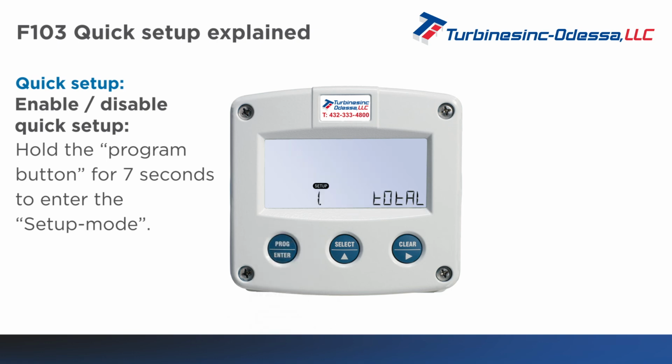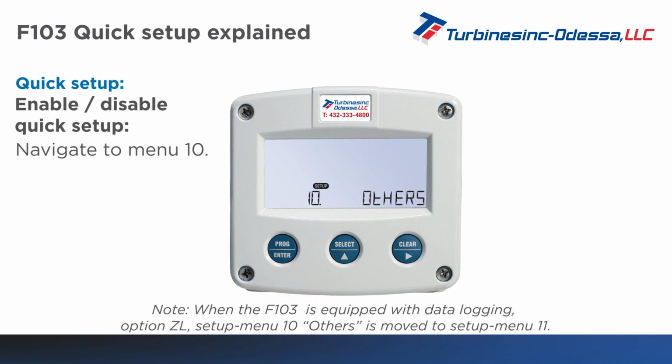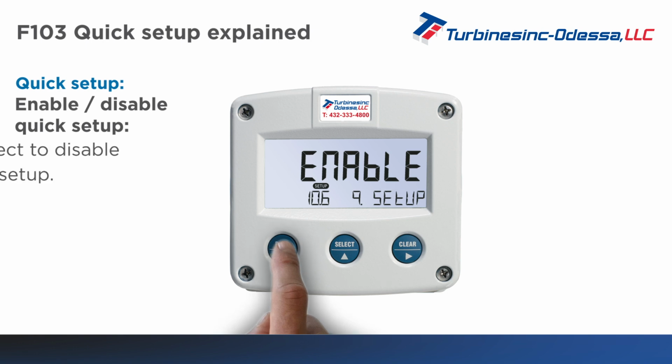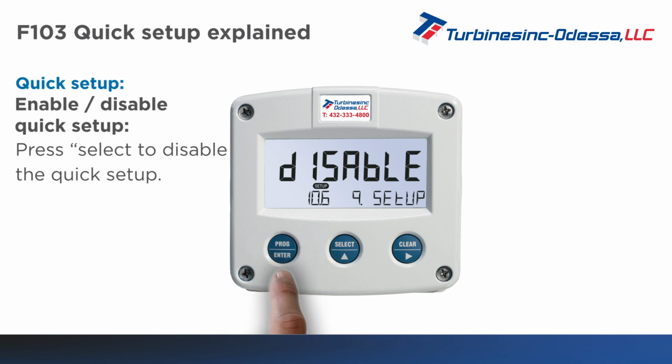Menu 1 Total appears. You can use the Prog, Clear and Select buttons to navigate through the menus. Use Prog to navigate to Menu 10 or 11 Others. Note, when the F103 is equipped with data logging, option ZL, Setup Menu 10 Others, is moved to Setup Menu 11. Use Select to go to Menu 10.6 or 11.6 Quick Setup. Press Prog to change this setting. Press Select to disable the Quick Setup. Press Prog to store this setting.